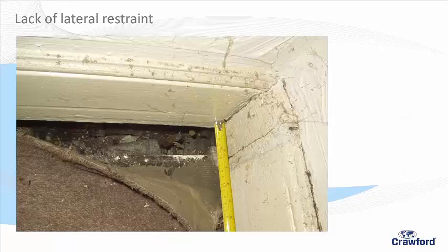And this is an example of me going to see a house which has got a hairline crack, and I was a bit interested because I thought this wall had fallen out, but there's no evidence of it. Now when I move this cabinet out, can you see what I see? Well, there's the skirting, and there's the wall, and here's the floorboard. That floorboard used to be there, or that skirting. That whole wall used to be there. If that wall's there, what's happened here? Someone's pieced in a bit of skirting. Can you see it? About an inch of it, by the way. So it's moved by 1 inch out, and the customer's put that in.